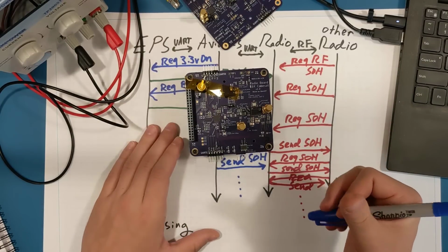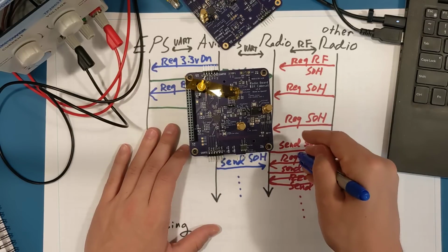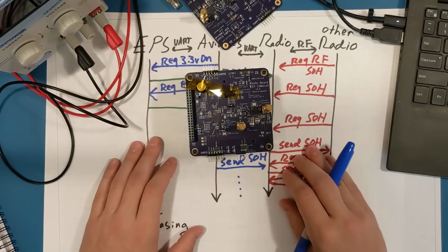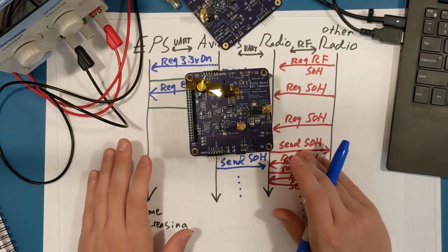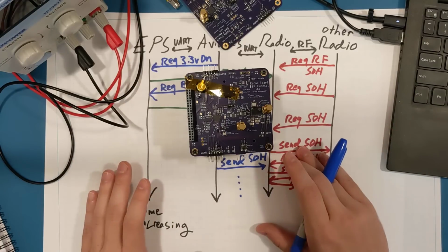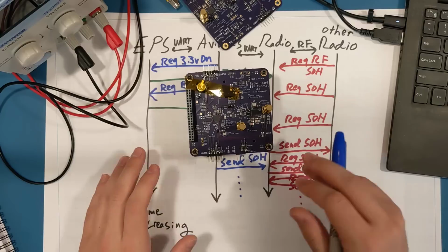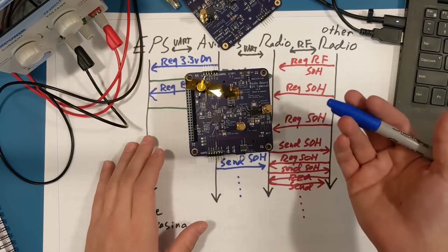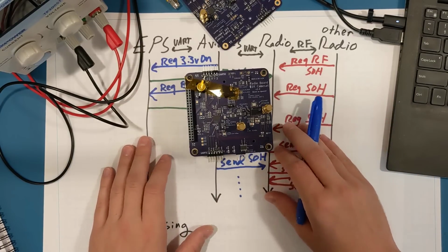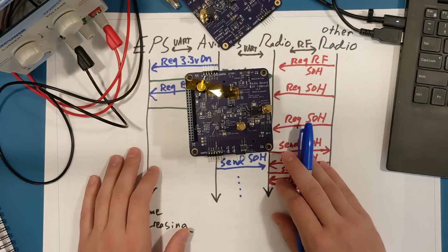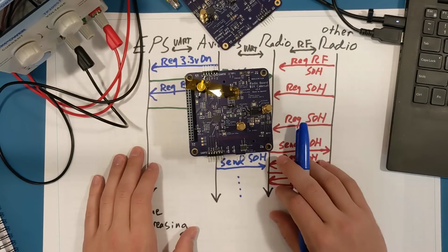It's important that you get the F32 variant because the OpenLST program, before I made any modifications to it, only had 150 bytes of free RAM. There's probably some stuff I can do to cut that down, but it's a pretty slim margin. As compared to the program flash, it has 32 kilobytes of program flash, and it only uses about 5 kilobytes of that, so there's plenty of room there for a larger program. RAM is really just the concern.